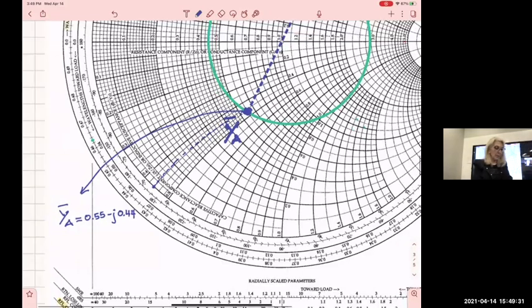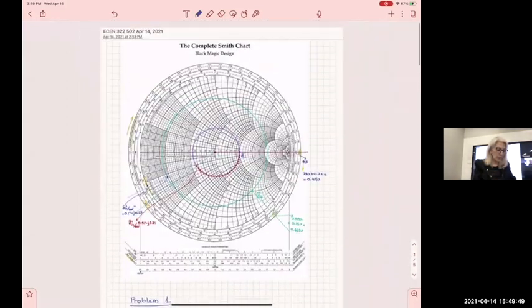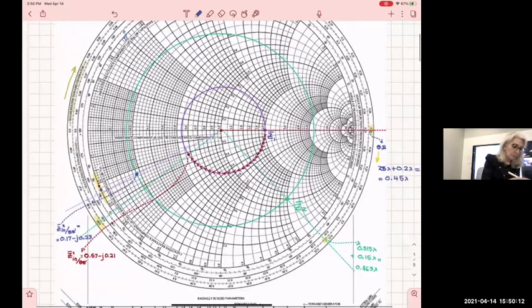All right, so practically, I find that I don't have to go and invert a complex number. If I don't have the capability, or if I am in a hurry and I am experienced on the Smith chart, that's how I'm going to do it. Why am I saying this? Now that I have both circles and both loads, why would I go and try to invert? I have two impedances in parallel, which means their admittances will just sum. The total admittance is one admittance plus the other. So why would I go and do anything? I can find it here by doing the following.